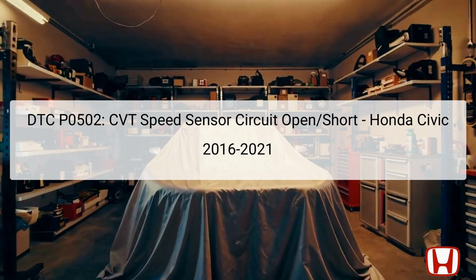Troubleshooting should begin with verifying the DTC and checking the relevant connections in the circuit. It's essential to understand that mechanical issues within the transmission can't cause this specific DTC, so diagnostics must focus on the electrical components and wiring.